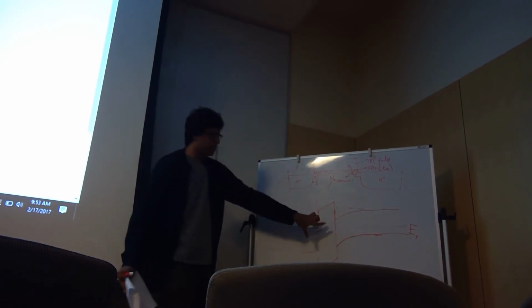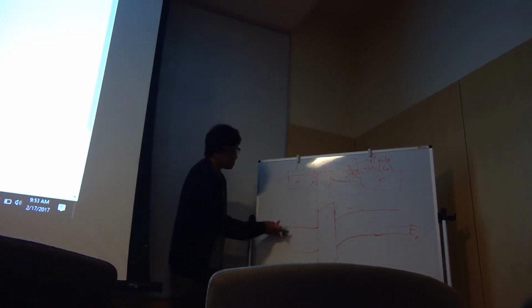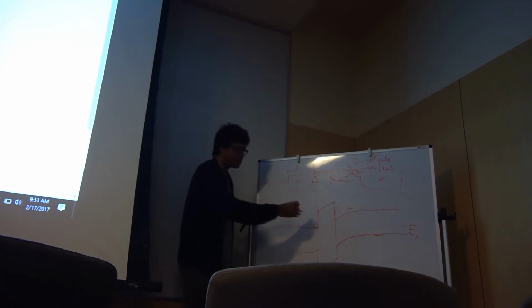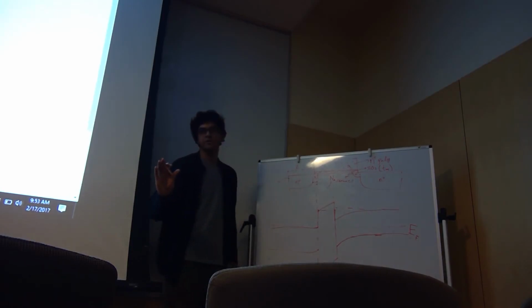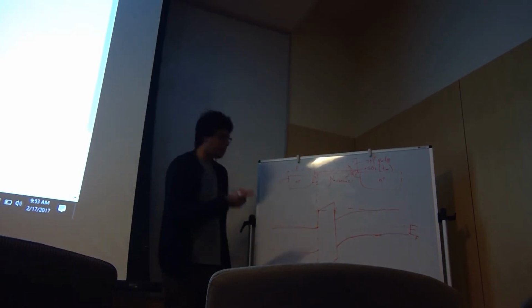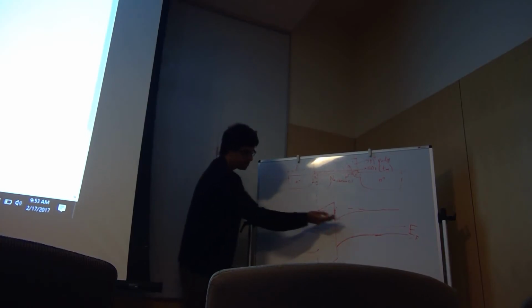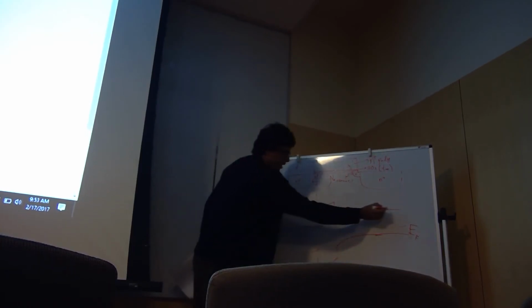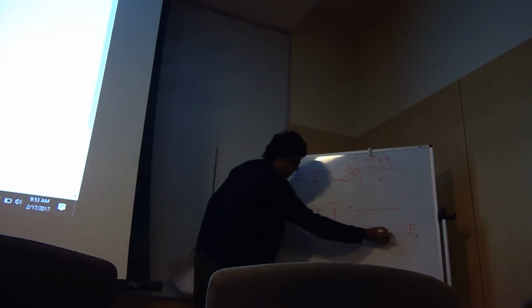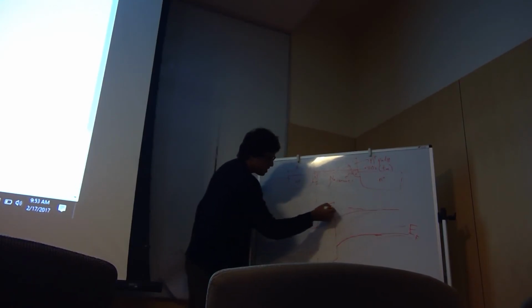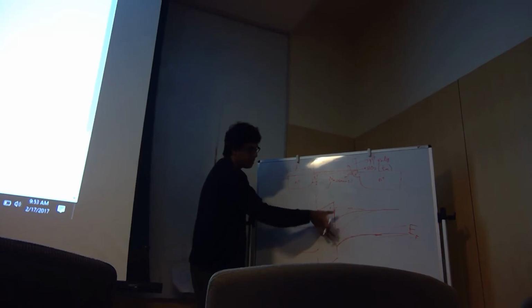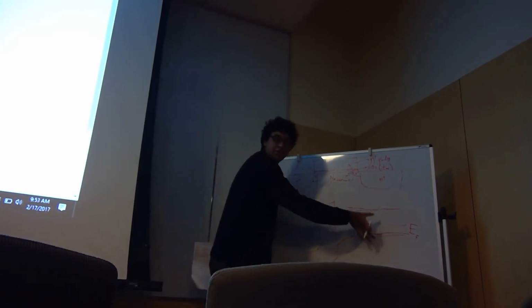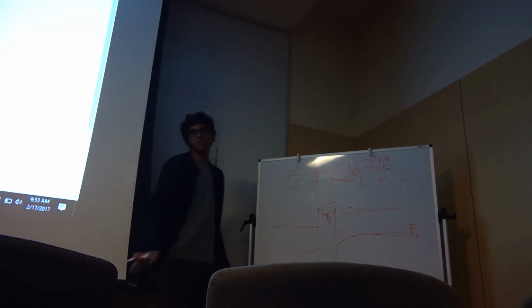Here, I'm not applying any gate voltage. The amount of voltage that I need to apply to make this whole thing flat, that is, make this straight and make this straight, is called the flat band voltage. That is what I gave the formula for. When you apply a gate bias, the Fermi levels will shift depending on the bias, and this will bend more and more. Ultimately, when this bending reaches a value of 2 times phi B, your electron concentration at the surface becomes the same as your hole concentration in the p-type material. And that's when you say your device has reached threshold.